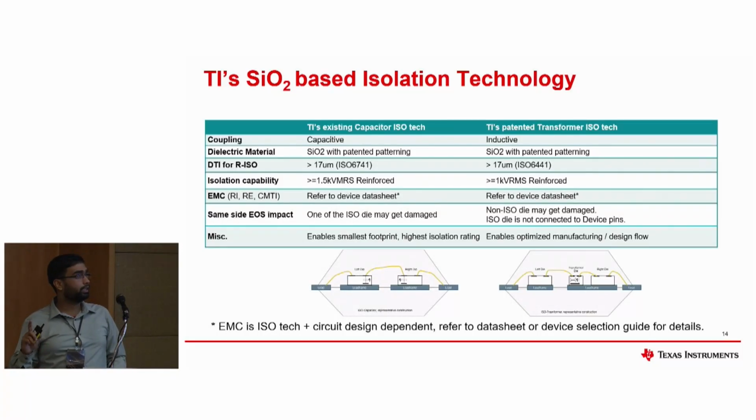Okay, that is a very good question. The advantage of the new one, if you know the series capacitive signal chain, is first that it improves our design flow cycle. Earlier, you designed a new part and had to take care of the isolation component embedded inside the communication die.